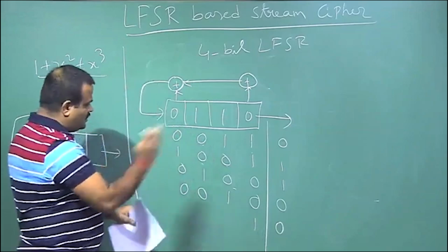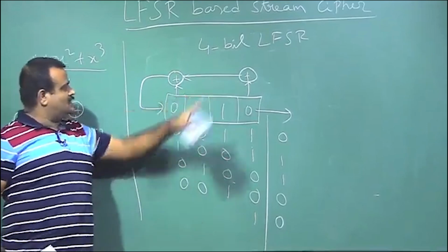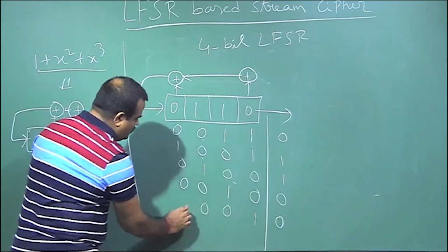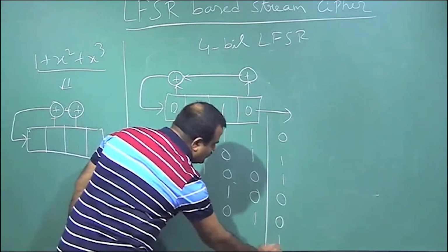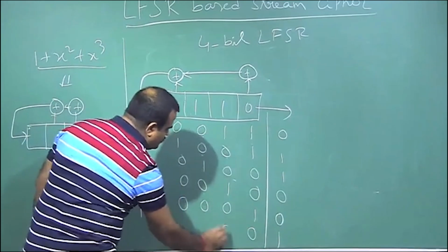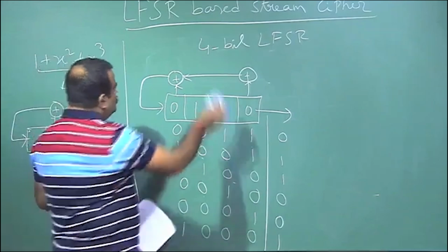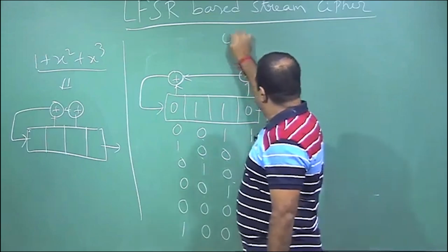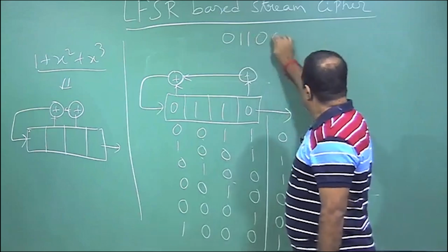So, linear feedback shift register. We are just shifting this by 1 bit, and we are taking the feedback based on this connection, based on the polynomial. So, this will be coming here, this will be coming here, this 2 is basically 0. Then we have 1 going there, and here this will come here, this will come here, this will come here, and this 2 is 1. So up to this we got 0 1 1 0 0 1.